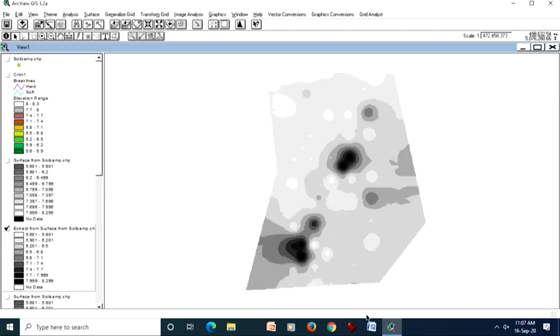I hope that by now you are able to get either of these software, or even QGIS or GRASS, which are open source software, and start doing the same exercises which I have done, and get a feeling for the data, how the system stores the data, how you can generate the data, and how you can compare different data sets, vector and TIN and raster, so that you will understand the efficacies or advantages associated with each type of data model, and of course the disadvantages of all types of data models, including your non-spatial data. So this brings to the end of this discussion.